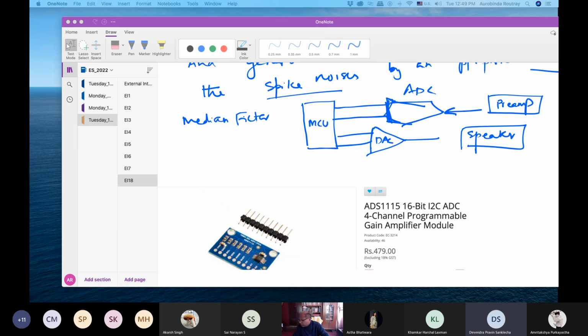All right. So this could be a problem. Sir, can't we directly use 2 ports for output as well? There are 4 ports too, but if it is possible to use, no problem. But another port is busy because you are using the interrupt, so possibly you cannot use one port. Therefore, you have to use only one port and do 2 consecutive writes and latch it for the 16-bit operation. That's what you have to do.